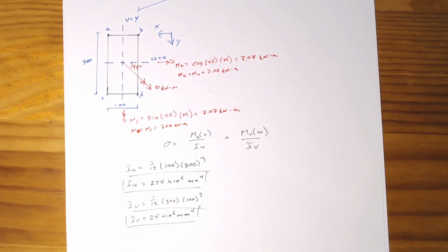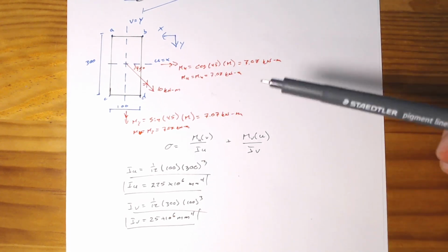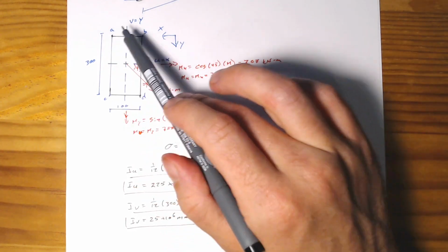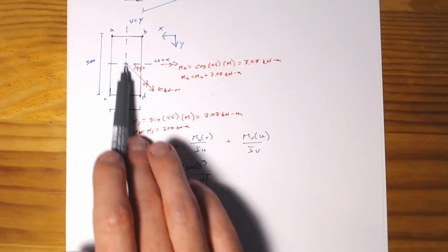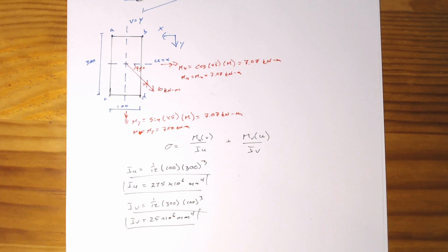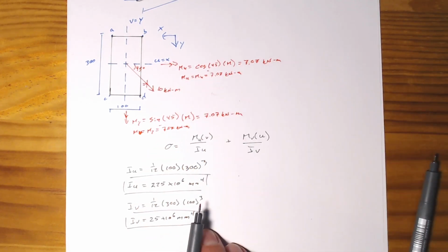Now we have all of our pieces, and as we looked at in our derivation of how to work out biaxial bending, let's take our points of interest, the corners effectively, and work out what the stress is in each of these. We just have to make sure that we stay consistent with our cross section and what our moments would be there. Both of these moments are negative moments, based upon the direction in which they're going, so we can just say this would be a negative and a negative, which again is going to put the top into tension.